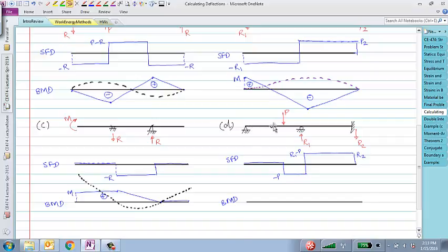In all of this part, all the way up to here, it has to be zero, right? Okay, so let's mark zero bending moment all the way up to here. Shear force is negative at that point. So we'll go down by some amount, and then shear force is positive. It goes up. Would it go to zero? No. And I should have actually marked the bending moment out here as well.